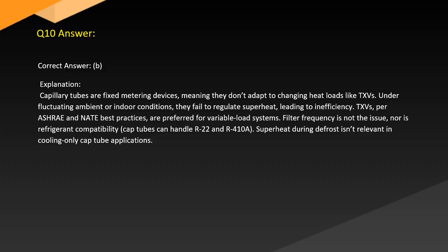Filter frequency is not the issue, nor is refrigerant compatibility. Cap tubes can handle R-22 and R-410A. Superheat during defrost isn't relevant in cooling-only cap tube applications.